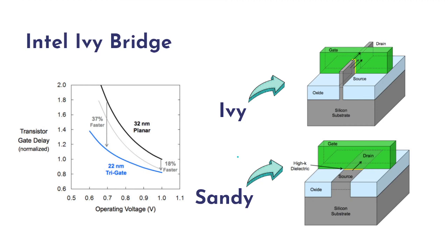There's a successor to the Intel Sandy Bridge, which is the Intel Ivy Bridge. This one is designed in 22 nanometer, and it has low power computing advancements. It has increased graphic performance and enhanced security capabilities. The speed up of the Ivy Bridge is attributed to the use of tri-gate as compared to the planar gate. We can see that here.